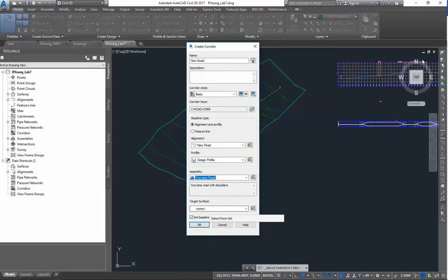So when we defined those assemblies and we put the cut and fill ditch, it was going to go find the existing ground, but it actually needs to know what it's trying to find. In most cases you're going to use the existing ground. Sometimes we have another surface underground, like the bedrock or some other piece, where we have multiple surfaces. But this is where it needs to know that. If you don't put that in there, those ditches won't even be created. It won't have anything that it's trying to target.